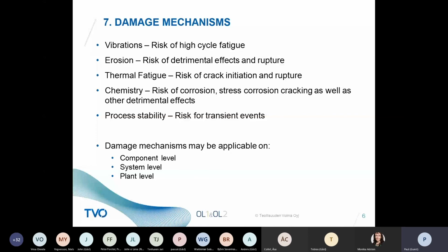If the flow is low enough, then the check valve is not pressed anymore to the top of the valve, but it will start hanging somewhere in between, and then it may start to clapper, which means that actually we did analysis on that, but also we had vibration monitoring on that side.